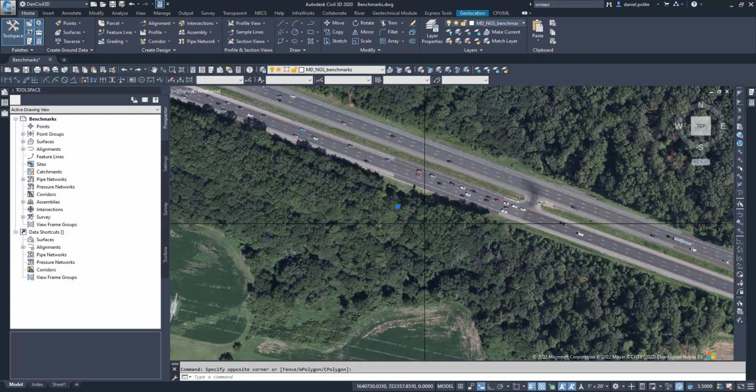If you don't have one close by, then the next best step to do is just keep your points the same elevation of what you surveyed them as. Leave those points alone as far as elevation. But if you did want to change those points, you could use the benchmark ones. That's the only time I would recommend if you wanted to change an actual survey point. Otherwise, you're just guessing as far as a point elevation.